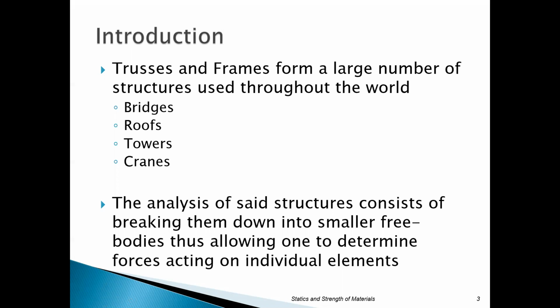What we've been doing in chapter 3 is primarily looking at one structure, but we're not looking at any of the interior elements within it. If we had a truss structure in chapter 3, we just looked at the support reactions. What this method will do is break this down into smaller pieces and attack each element.